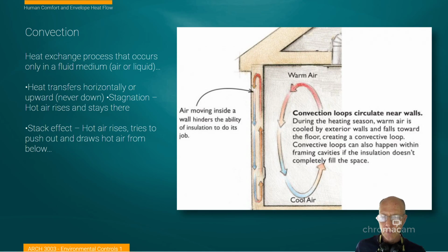In the interior environment, it can both create draft and it also can create thermal comfort. In the case of radiators, many times they're placed in front of windows and they use the idea of heating the air to create a thermal blanket across the surface of the window, and it cools slightly and comes back down into the center of the room. So we use that convection in some cases in rooms to help distribute the heat in the room.